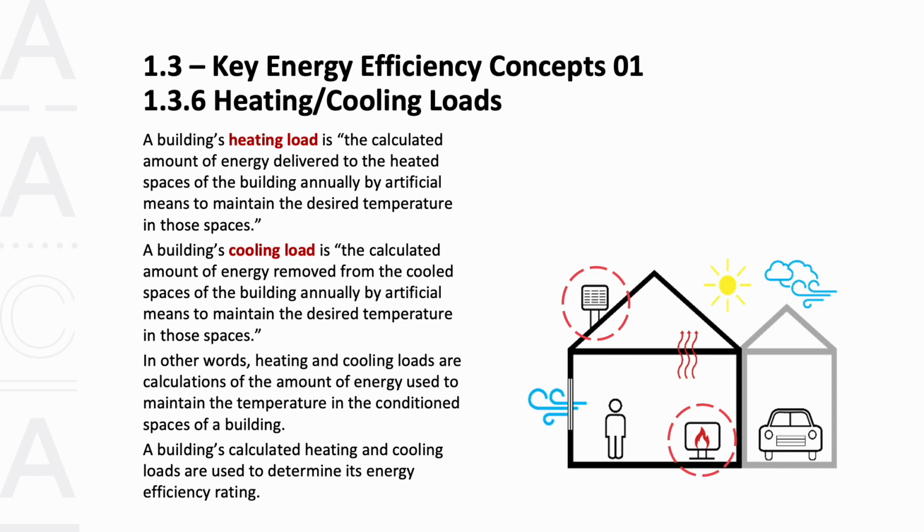A building's heating and cooling loads are the key factors that determine a building's star rating under the various energy efficiency rating schemes. Only NatHERS software allocates a star rating to buildings. Software approved for use in H6V2, which is verification using a reference building, is unlikely to allocate a star rating. The classification of conditioned space in a building makes a difference to the calculation of heating and cooling loads, and therefore the building's energy efficiency star rating.